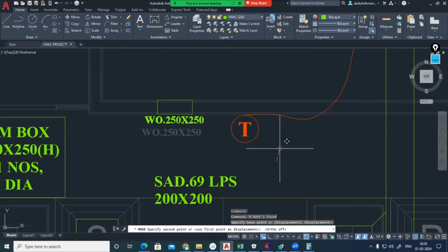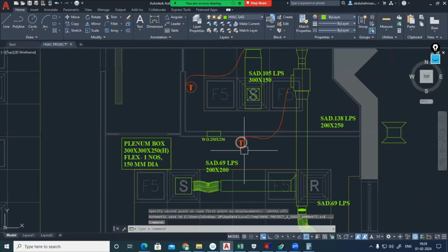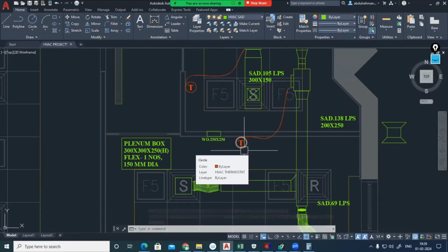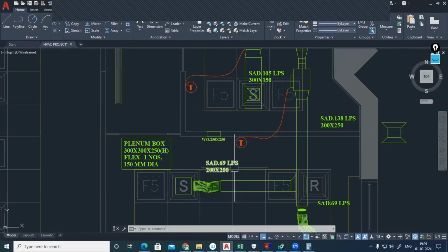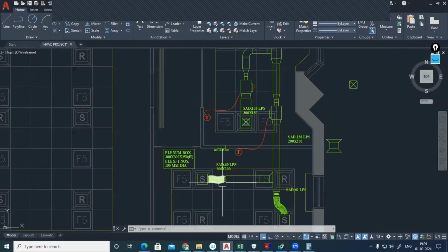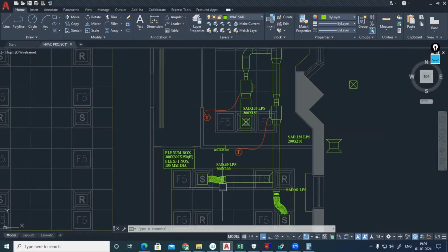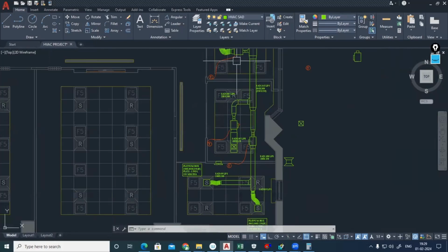So you have to make sure that when you are designing the system, wherever the machine is delivering the supply, from the same space, the return path should be there. Otherwise, the recirculation will not be completed. The machine is not in a position to understand the temperature within the spaces if it is not recirculating the return. Okay, so that's why. Now from this room to here, the return is coming. Now from this room to there, it has to go.